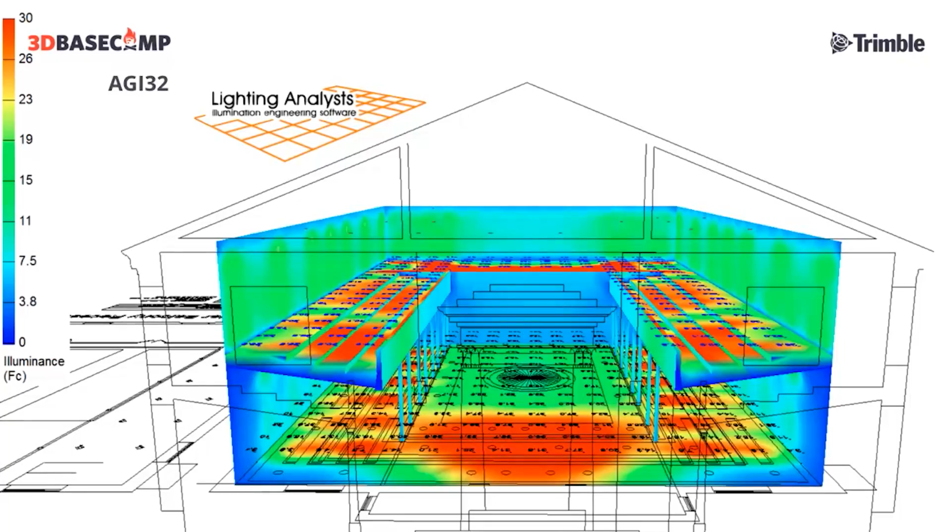and graphically show this as a mapping on your screen here. You can then take that SketchUp model and export it to programs that really do true analysis of lighting. So AGI 32 does that. So you can export your SketchUp file to AGI 32, and it will do more of your accurate light calculations.